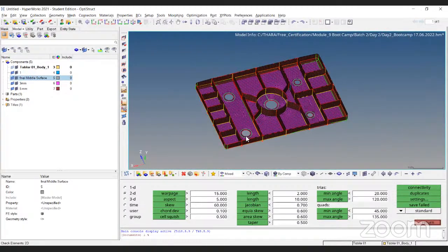If you have 100 elements and the same 100 elements are duplicated, it becomes 200 elements, and then the component becomes very stiff. Again, if the component is stiffer, there will be less stresses or less deformations. So for this reason, carrying duplicate elements is dangerous.